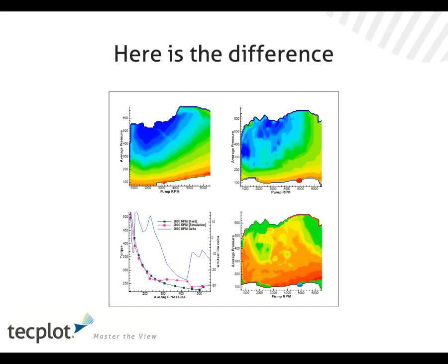To do that, you would probably need to define a new coordinate system that unwrapped the wing, the surfaces of the wing, and then do your kriging in 2 dimensions in the new coordinate system that, say, runs from the trailing edge around the leading edge back to the trailing edge, and then you would be able to do kriging.